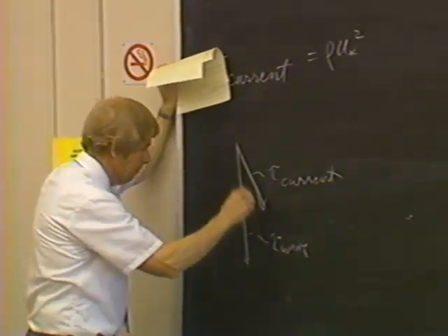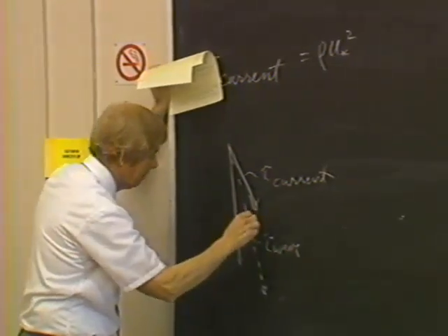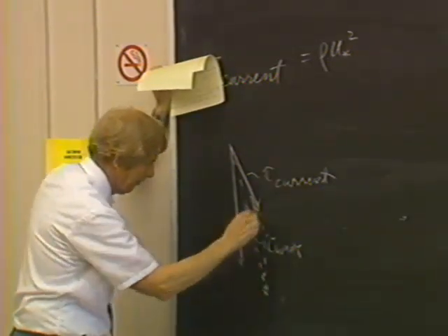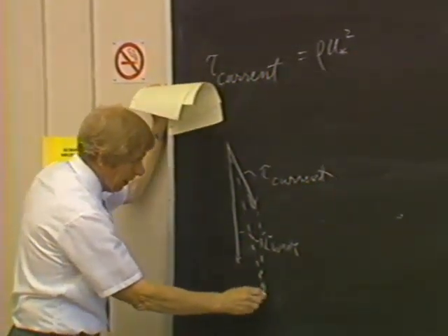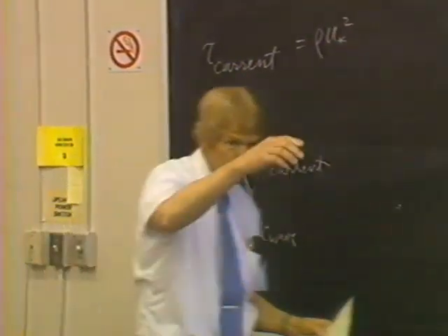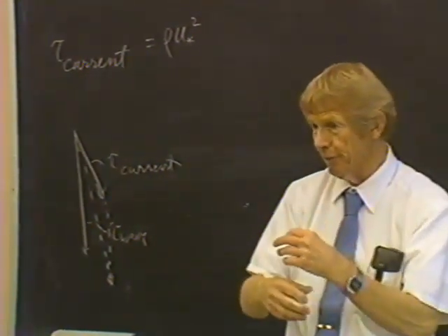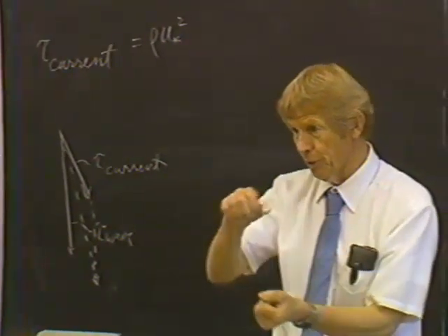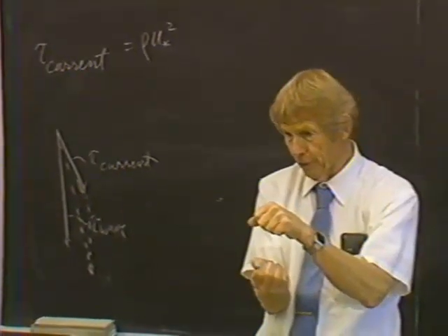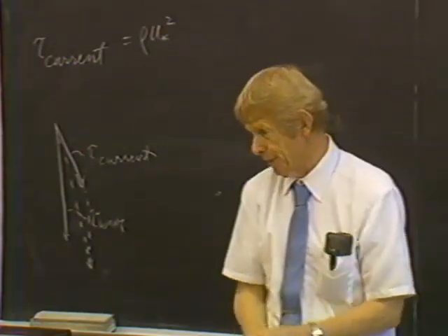The actual value, however, will be a little bit higher than that. And the reason is that the orbital motion under the waves enhances the mixing, the momentum transport that we talked about before, so that the effect of the waves is to either slow the current or, for a given current, to increase the momentum transport.